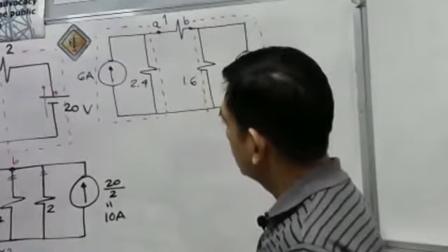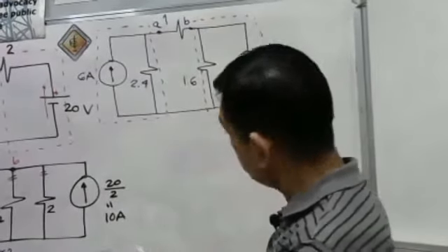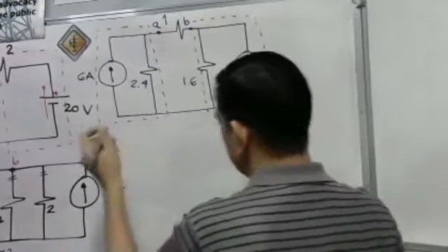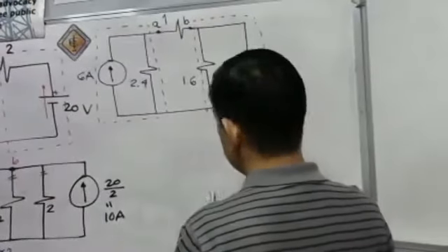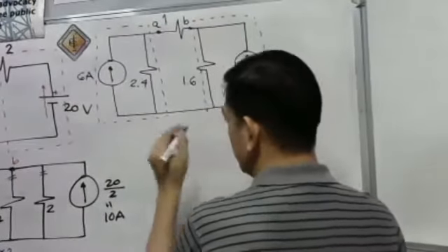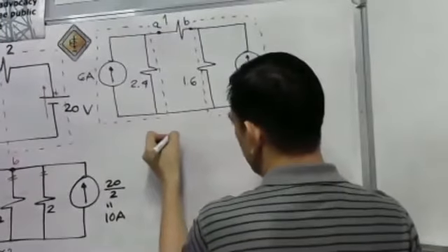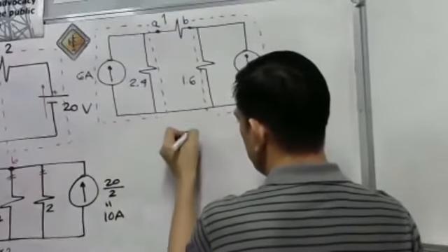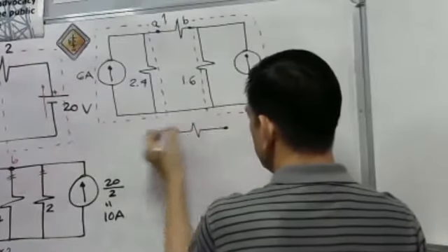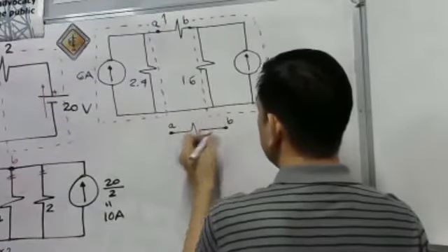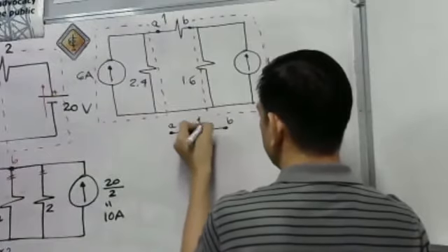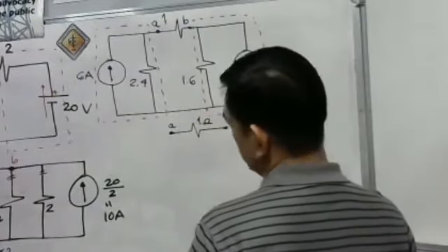So how is it? It's simply, we'll be having a series resistance in series with the Thevenin's voltage. I will draw first the point A and point B. This is our 1 ohm resistor, our load resistor.